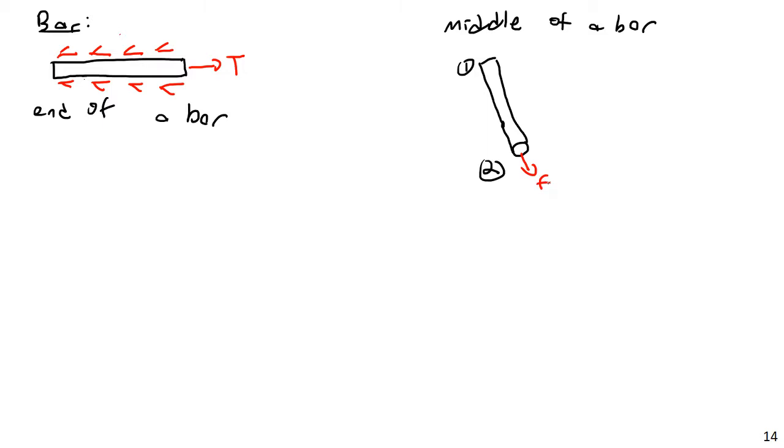fs2, that would be the stress in the steel at end 2 times area 2, or maybe just times the area of the bar. It's the same bar, so just times AB. And maybe this would be fs1 times the area of the bar. So if we had a differential element, it is possible that we would have different stresses, different tensions at either end, and then some sort of stress in the middle, distributing and connecting with the concrete. Something like this here. And across this, there may be some average stress, mu. Mu would be the bond stress.